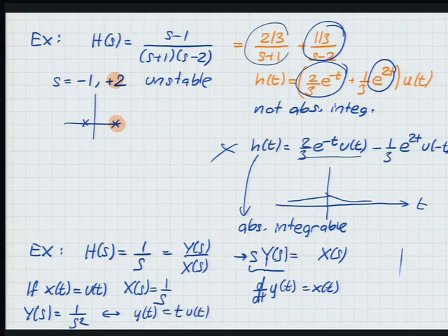That you could also have concluded just by doing the convolution. This is u of t. Input is also u of t, so you flip it and drag it. And then the area is the output. So as this keeps growing, the area grows linearly. That's why you get t times u of t, right? Isn't it nice to be bilingual, frequency domain, time domain? You can do these things as you wish, whichever domain you're in.